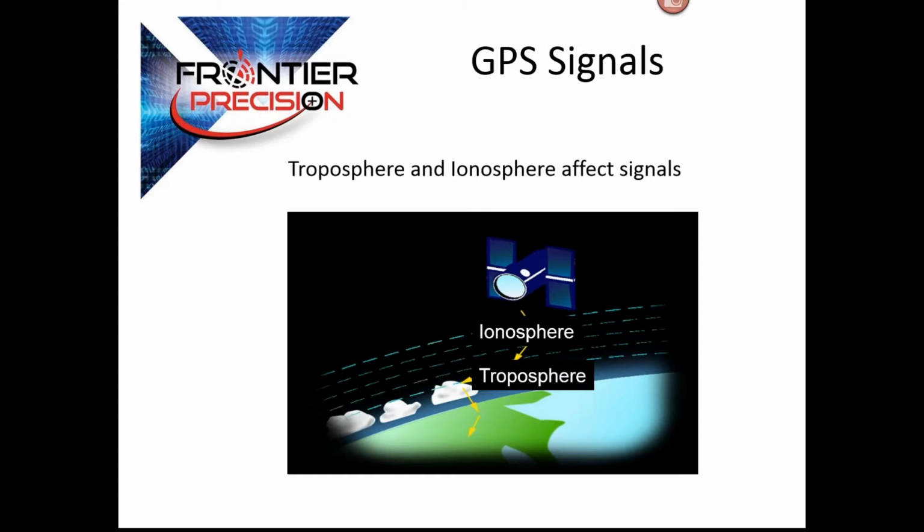So these conditions delay the signal a little bit, and that delay translates into positional error. Even though we can predict what a typical trip through the atmosphere will do to a signal and subtract that from actual measurements, since no single trip will be exactly typical, these corrections aren't perfectly accurate.